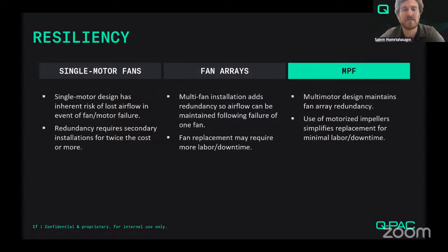And there's lots of reasons why it's becoming harder and harder to maintain and service those. There's a lack of experienced labor that can service them. There's not as many people out there that are building 6-inch diameter blower shafts for these massive fans in certain places. And facility managers are seeing a large drop in people that are capable maintenance mechanics that can maintain these things. But anyway, the simple answer is that the single motor fan does not have redundancy. If you lose it, you lose airflow. In a lot of cases, what people would do is they'd actually just have redundant air handlers. So again, it's more than what you need to achieve your goal.